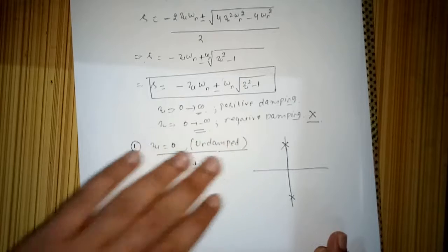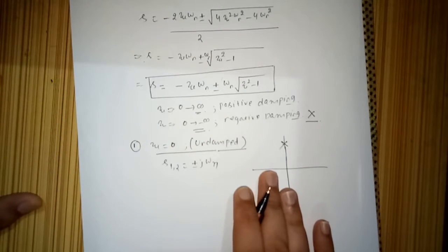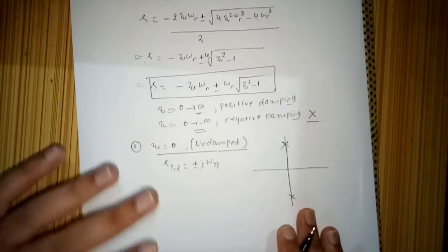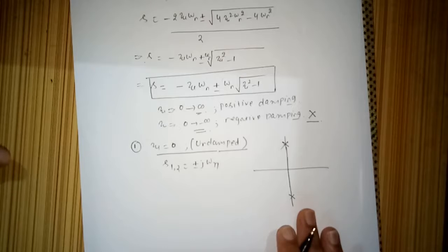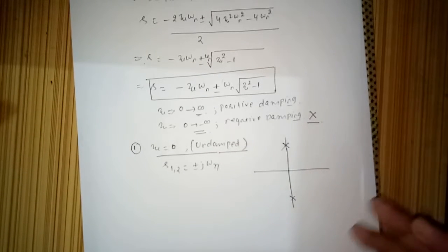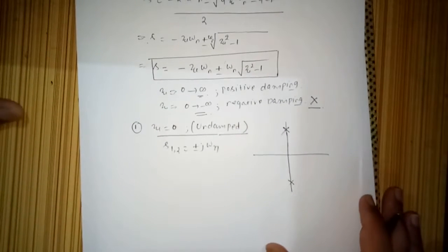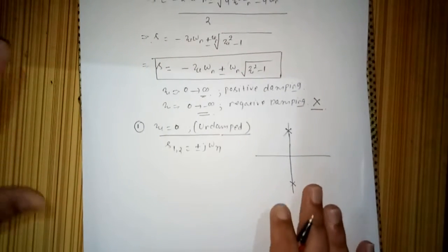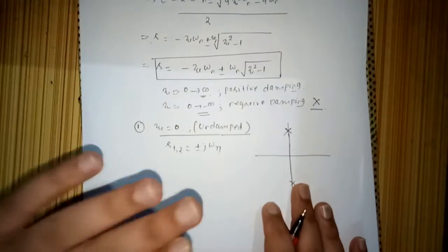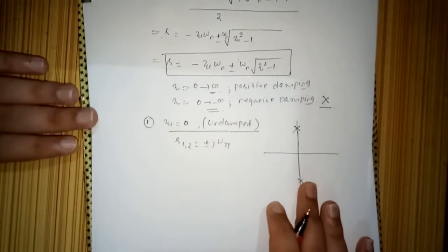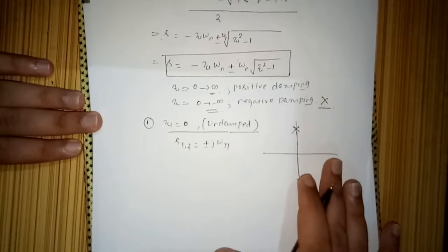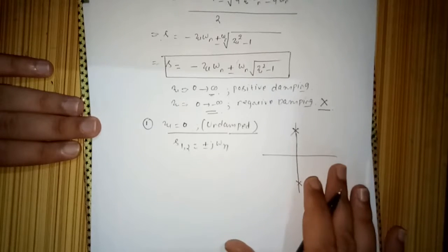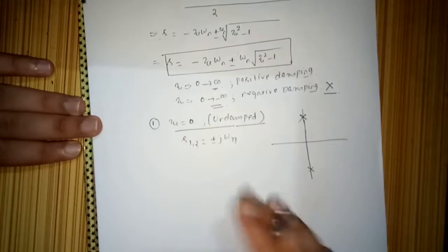So this is not a stable system. This is generally called marginally stable. Marginally stable systems are nothing but unstable only. But we use these kinds of systems in our oscillator circuits; for our control system purposes, these are not stable systems, right? We don't desire this kind of system. Also, this will have a sustained oscillation with its natural frequency. That is not desired. Sustained oscillation is not desired in a control system.